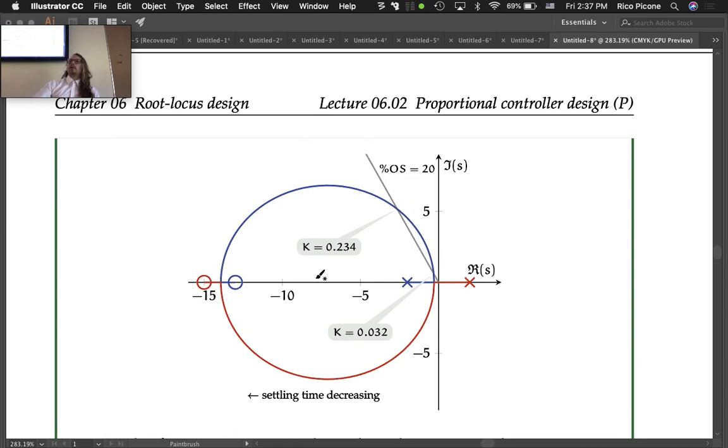So what I would recommend, if you want to get real tight with meeting your spec, you've got to keep in mind that there are two local minima here. There's going to be one that corresponds to the lower gain and one that corresponds to the upper gain. So you want to probably do a sort of by hand process to get you to the right minimum, and then do your loop from there. So if you really want to refine it down to like 5 digits of precision, like 19.999% overshoot or something, then I would recommend starting at a point that's close to where you want to be and iterating from there. Otherwise you might find this other minimum, and that is not what you're looking for, because you have this other design criterion, the settling time, that you have to consider.